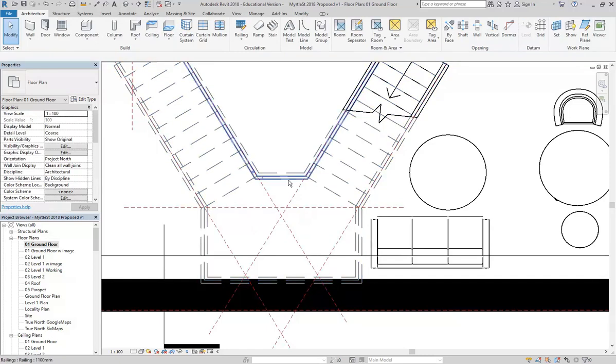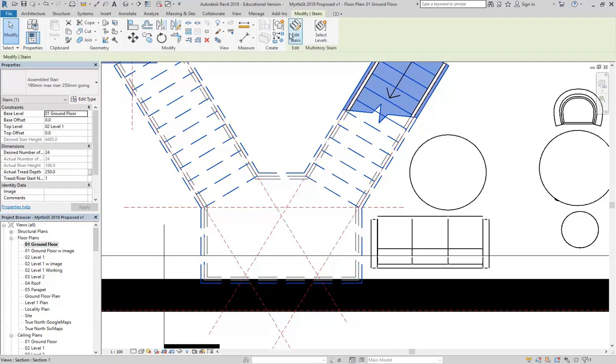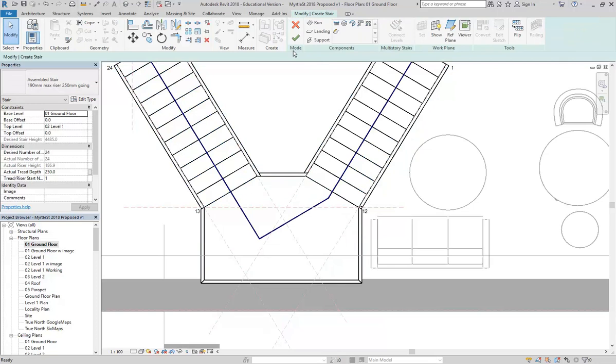So what happens if you have a stair that's not attached to a typical? That's okay. Yeah. So you might need to have posts to support the stringer or the outside supports, but otherwise, yeah, perfectly fine.